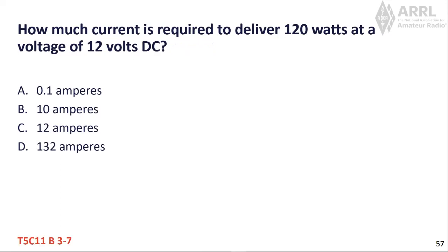How much current is required to deliver 120 watts at a voltage of 12 volts DC? You would have to have 10 amps to get 120 watts, and that would be answer B, 10 amps.